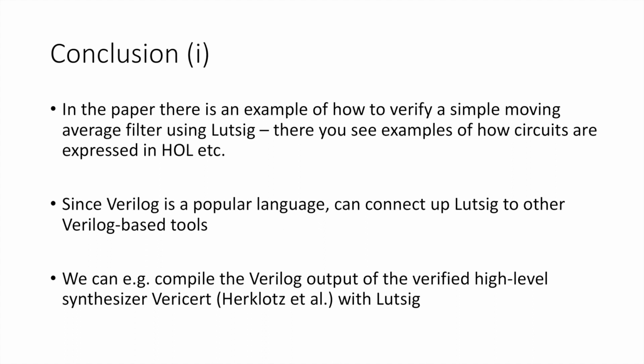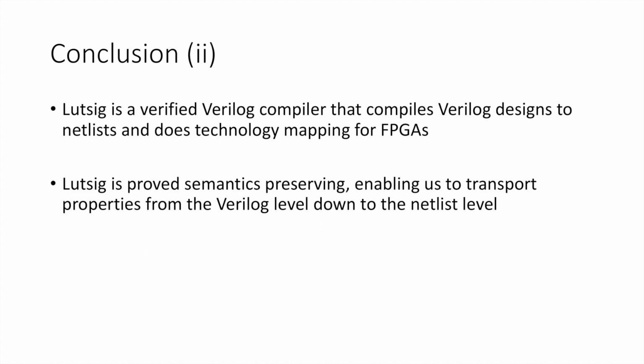And since Verilog is a popular language, you can connect up Lutsig to other Verilog-based tools. So, we for example show that we are able to compile the Verilog output of the verified high-level synthesizer Vericert using Lutsig in the paper. All in all, Lutsig is a verified Verilog compiler that compiles Verilog designs to netlists and does technology mapping for FPGAs. By verified, we mean that Lutsig is proved semantics preserving, and this enables us to transport properties proved at the Verilog level down to the netlist level.